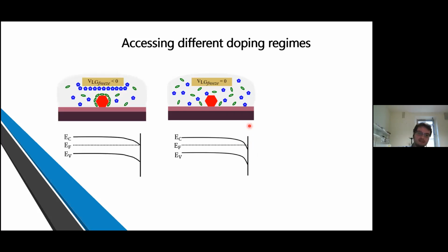If we apply a negative counter-electrode voltage, we induce an ion accumulation at the surface of the nanowire, and thus we apply an electric field which performs upward band bending, thus depleting the carrier concentration present in the pristine regime.